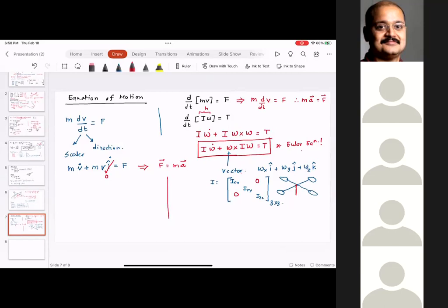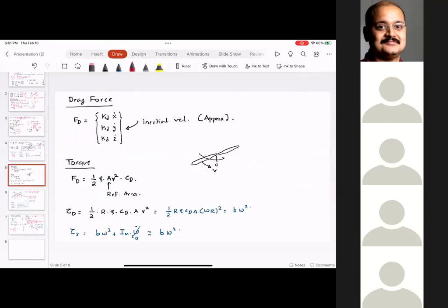But before we go to angular velocity, let me conclude what we have over here. The equation of motion in translation, the exact same equation that we derived in last class, is written as m x double dot is equal to the gravity, or the weight, which will always act in z direction. So there is no component of weight in x direction, no component of weight in y direction, but it has the weight, mass multiplied by gravity, in the z direction. Plus, you have some thrust that is coming. Remember the equation for thrust that we derived earlier, T1, T2, T3.